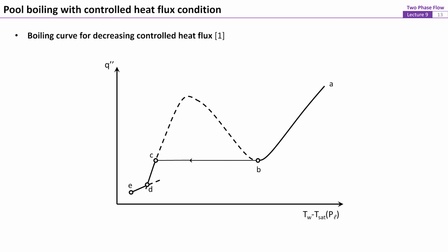In addition, with the active sites remaining active during a cooling process as previously mentioned, the cooling curve moves from point C to D with a continuous transition, rather than having any sudden change in temperature. Eventually, the excess temperature is too low to sustain any active site of nucleation, and the heat transfer is only by natural convection. This is presented on the segment between point D and point E.